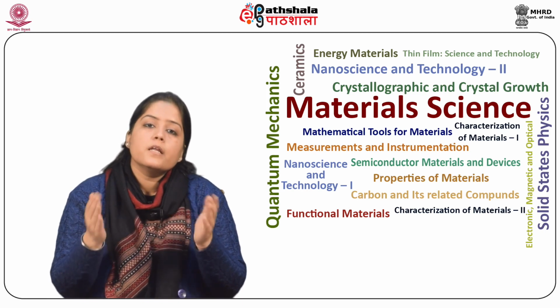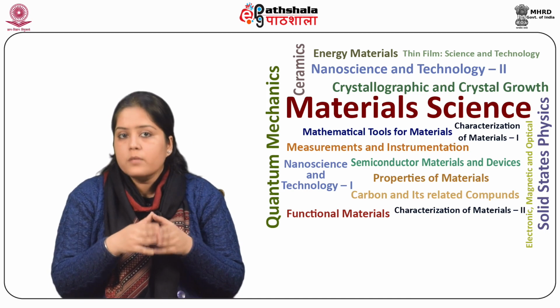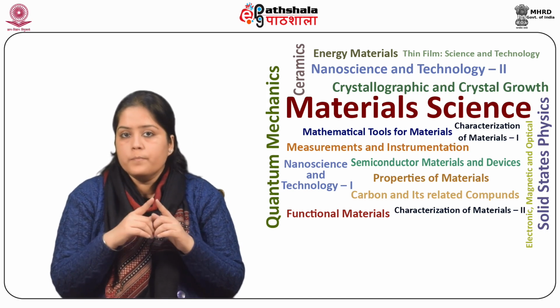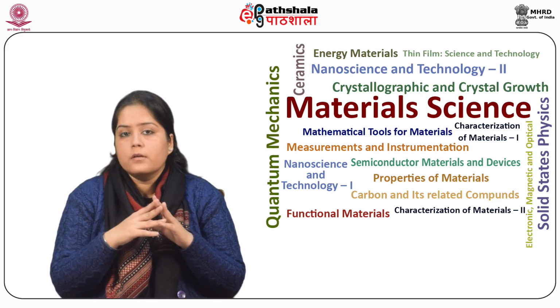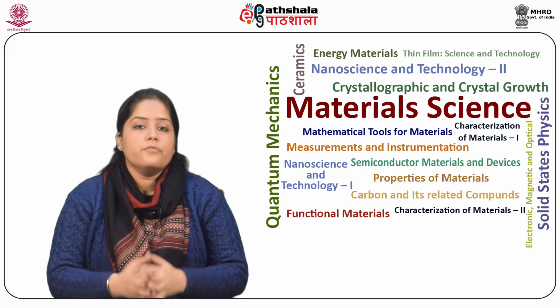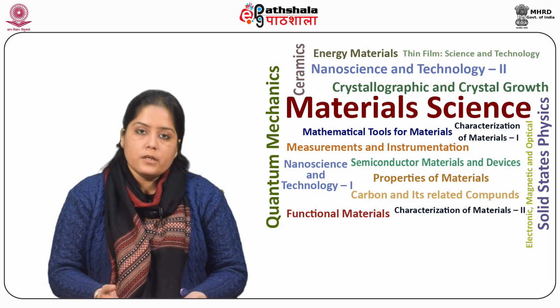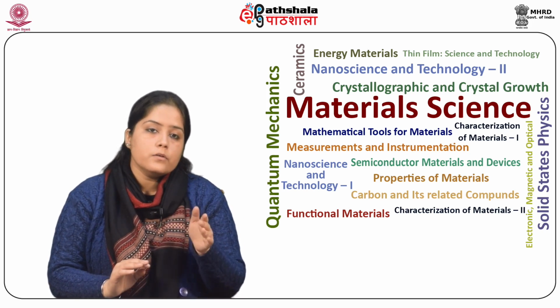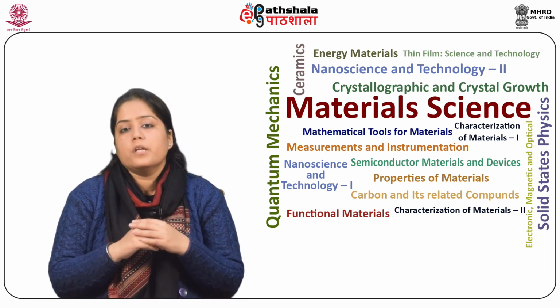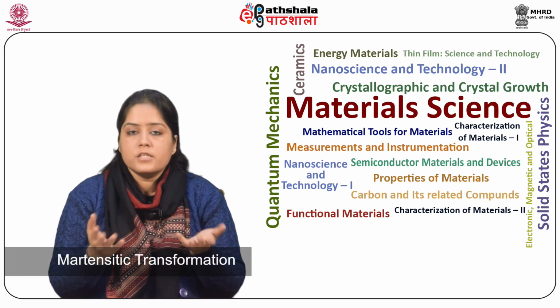However, inclusion of large amounts of alloying materials in uranium may result in brittle formation, which adversely affects the ductility and fabricability of the alloyed uranium. Another route of hardening the uranium alloys is its martensitic transformation.